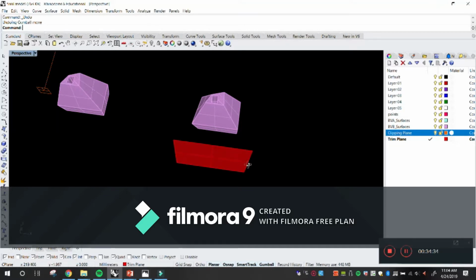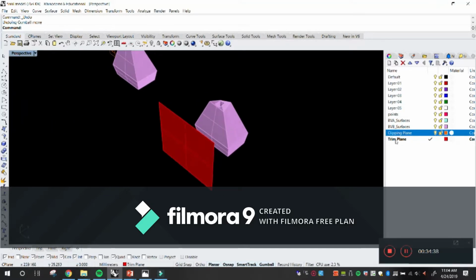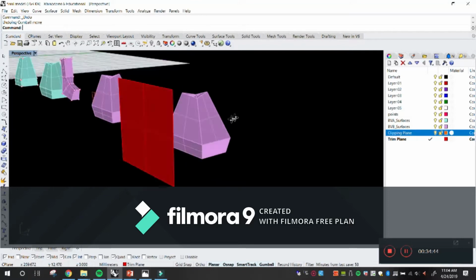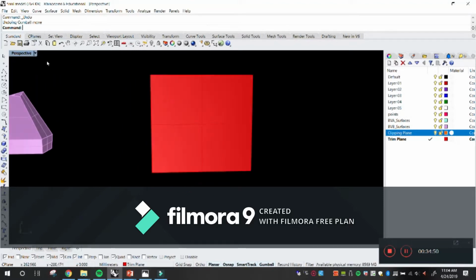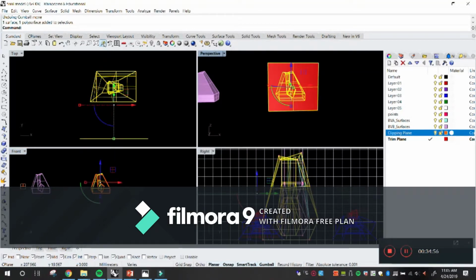All right guys, one more time. We create a new layer called the trim plane, or maybe even the split plane, since we're doing a Boolean split, but either works. Now for this one, I'm pretty sure it does have to be the size of the object that you're trying to split.